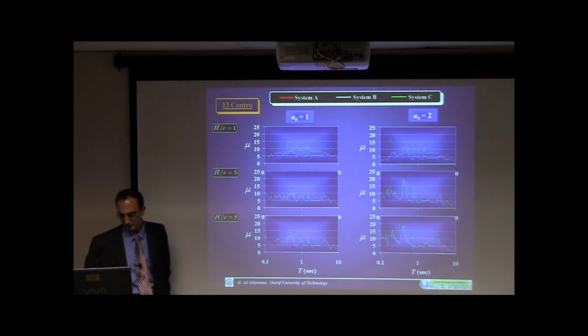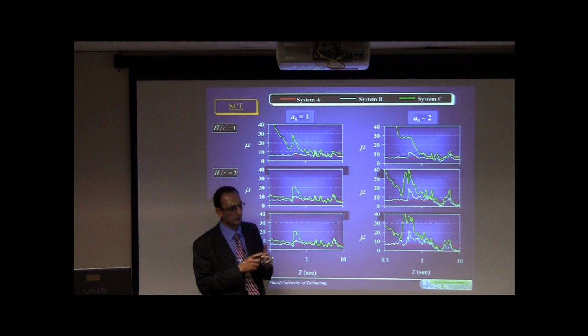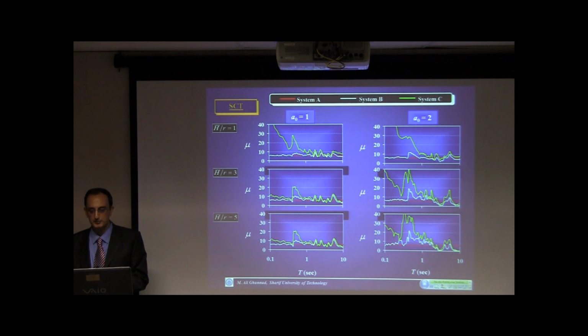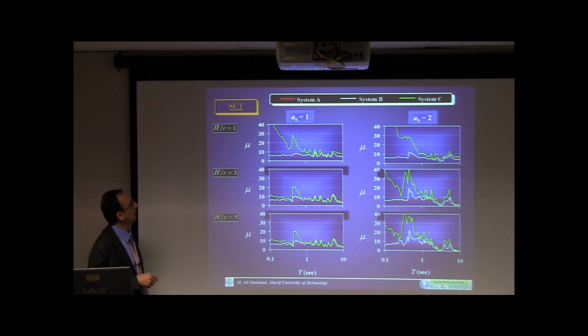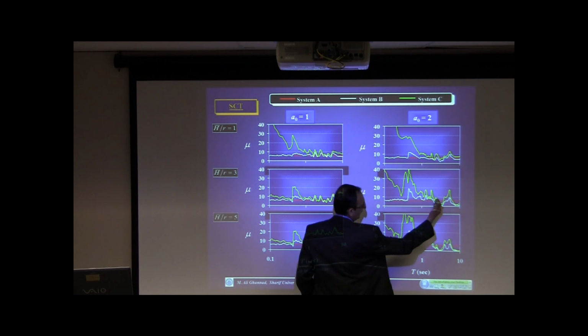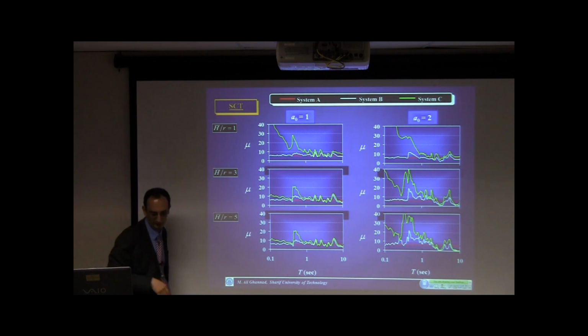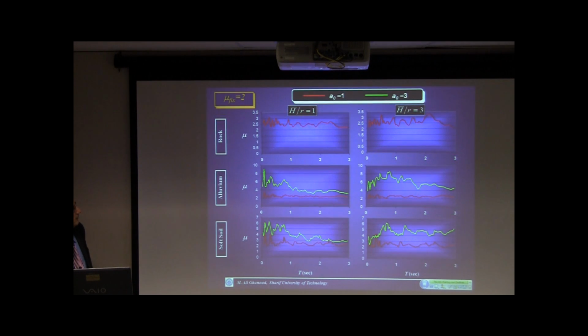Okay, and this is for SCT, the Mexico City earthquake. Of course, the results of the nonlinear response of structures strongly depend on the predominant period of the record. And for this record, which is a very long period record in soft soils, this phenomenon has started in the long periods here, and you can expect very, very large values. Of course, it is meaningless, but it means that the structure is not safe using that.